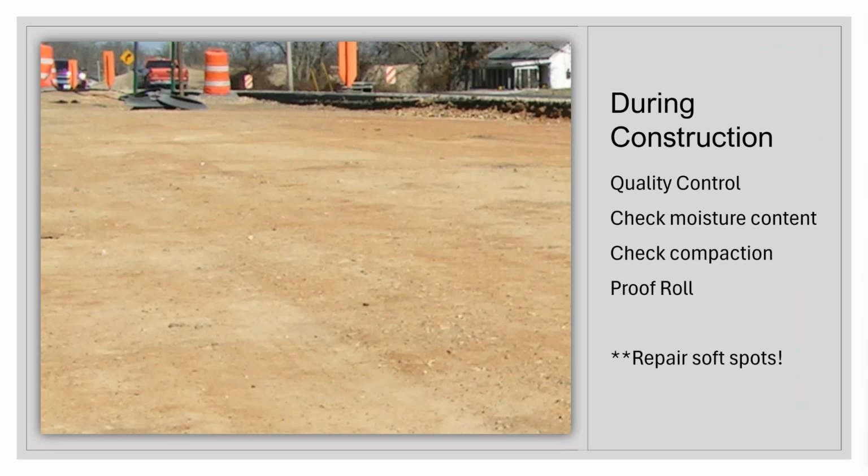And this is when you can get to it to fix it. So this really is the time that you need to have an eagle eye on all of this area. Make sure you don't have those soft spots, because if you find it 2 years from now, after it's covered up with pavement, now there's a pothole, you're having to dig through the pavement, cut out the base, cut down into the subgrade. And right here, we have easy access to it to do what needs to be done right there on the front end.